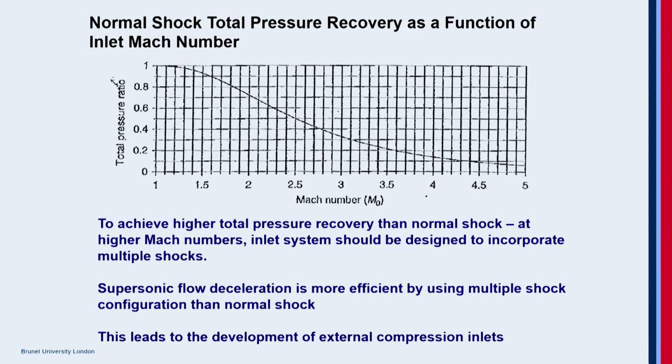So as I did mention this morning, supersonic flow deceleration is more efficient using multiple shocks configuration than normal shock. When you use multiple shocks, this is how the graph will shift. More number of shocks. So this leads to development of external compression inlets.